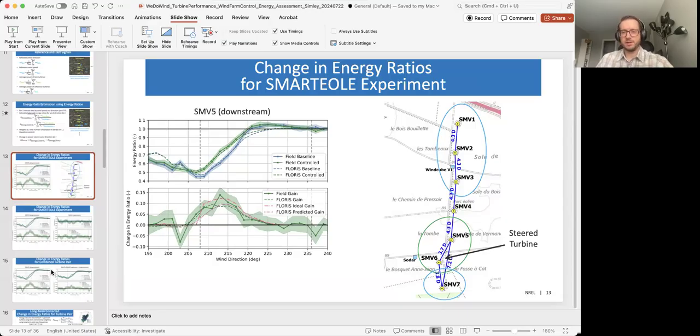So a 1 second wind direction or wind speed measurement from our reference turbines wouldn't really correlate with the power at the test turbine for that 1 second period. But if we use something more standard, like a 10-minute period, then the wind direction could be changing so much within that period that it's really averaging too many different conditions together.